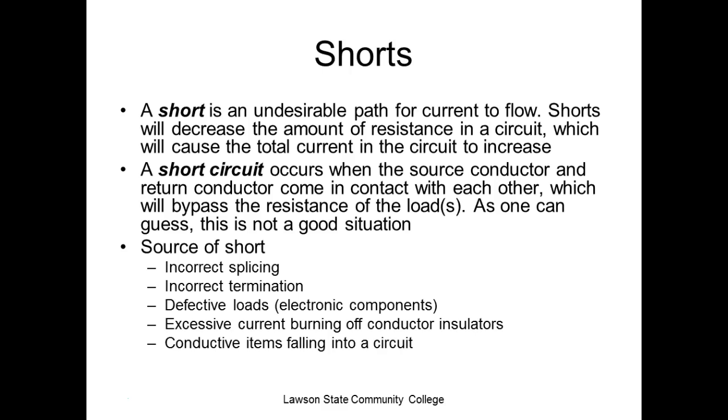Of course, the big one is this second one, a short circuit. So there's a difference between a short and a short circuit, even though a lot of people misuse that term. A short circuit occurs when the source conductor and the return conductor come into contact with each other, which will bypass the resistance of the load. So if you have a short circuit, what's limiting the current in the circuit? Just the wire and the internal resistance of the source.